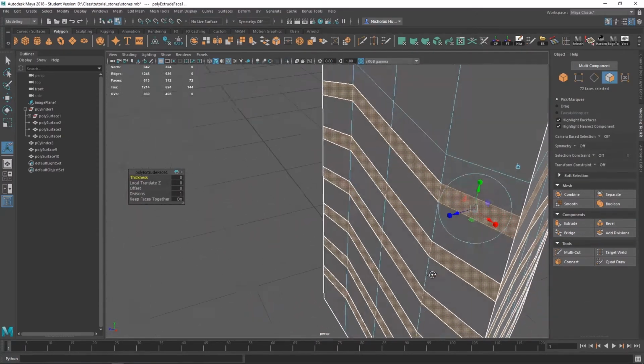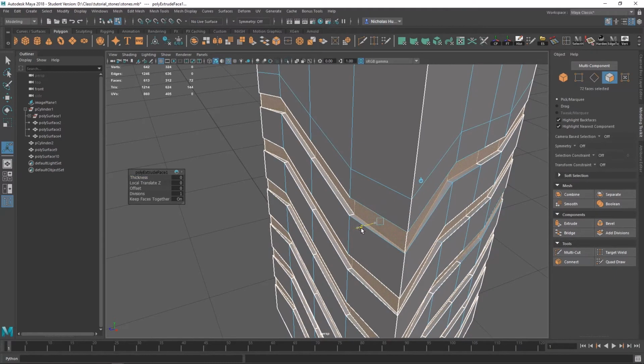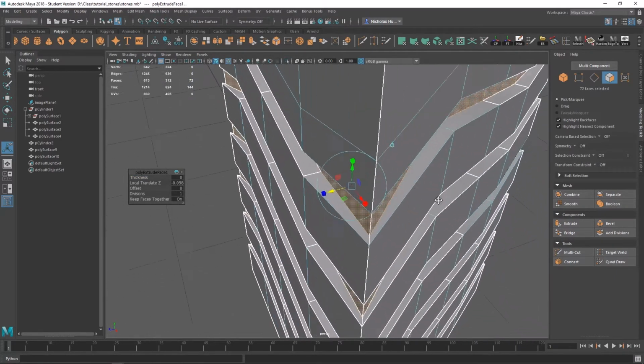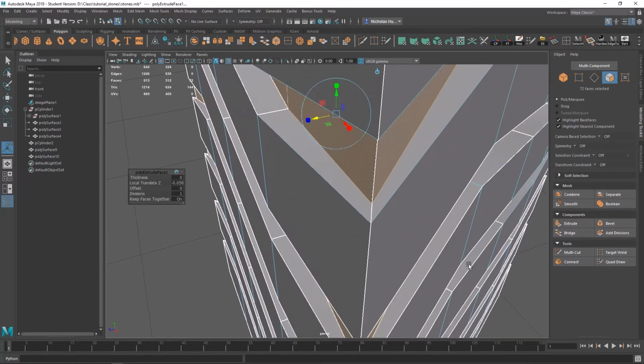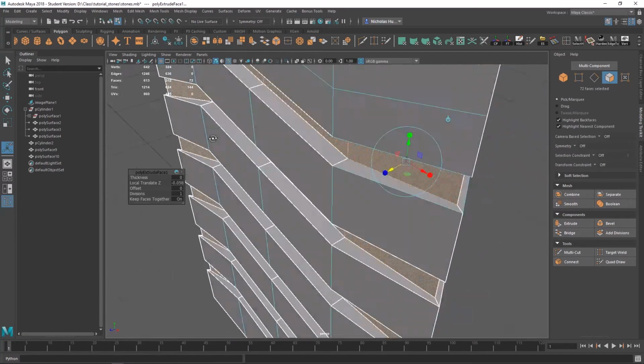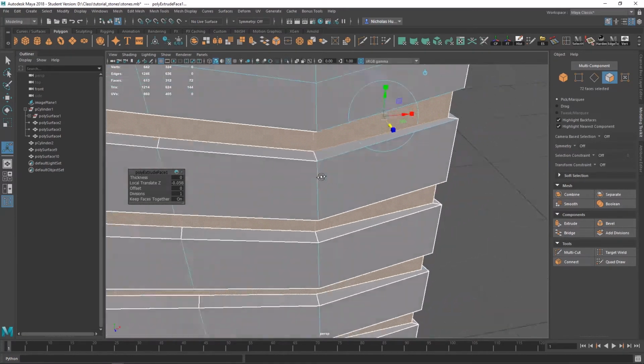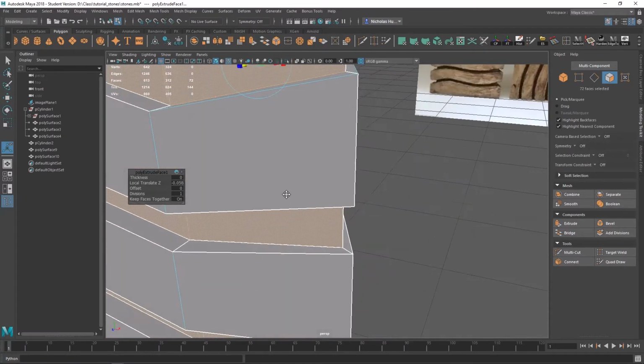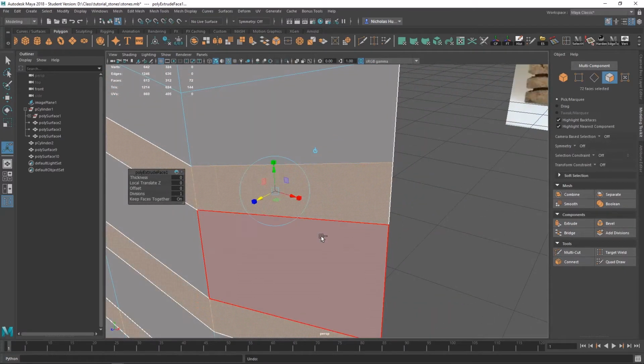And you can either play with this gizmo, you can push it in until you feel that's right. However, if you're doing the push-in method, I don't know why this is, but if you notice, this is longer than this here. And it's not going to give you a complete inset. So what I'm going to actually do is Control Z, and I'm going to use thickness here.